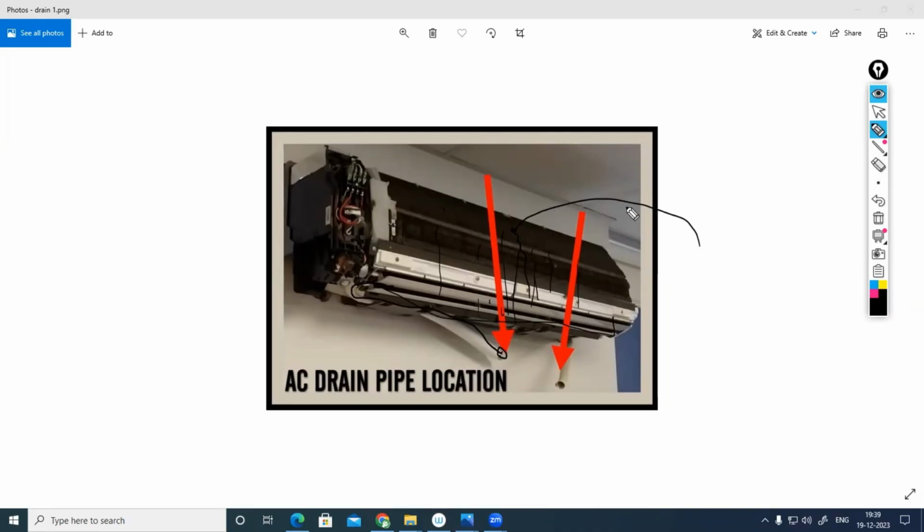But unfortunately, when this moisture present in the air has contact with the cooling coil, on the surface of the cooling coil and inside the machine, we have a lot of contamination. Dust particles are there. That's why this water gets polluted. If you purify this water, then you can consume it. Purification means you have to do sand filtration, activated carbon filtration. Then reverse osmosis is also mandatory, depending on the quality of water you are getting from the atmosphere. Anyhow, RO we can sometimes avoid. Just by sand filtration and so on, we can make this water pure.